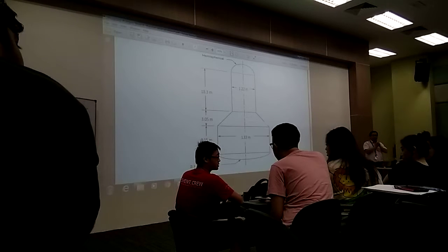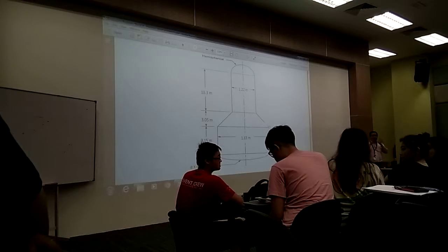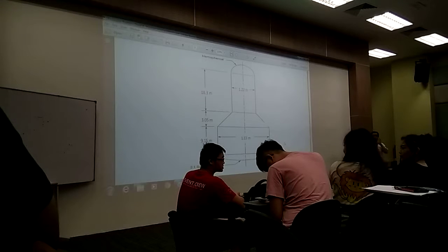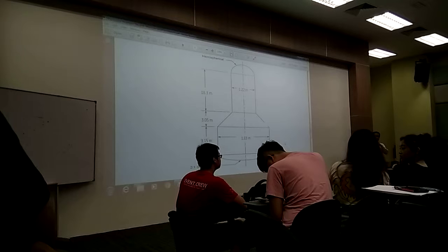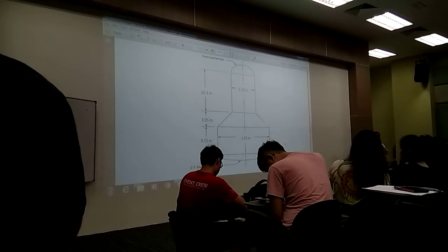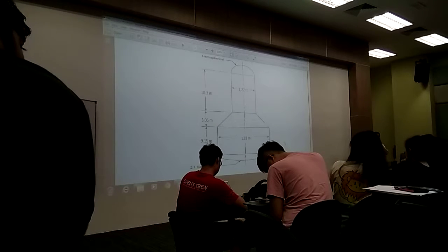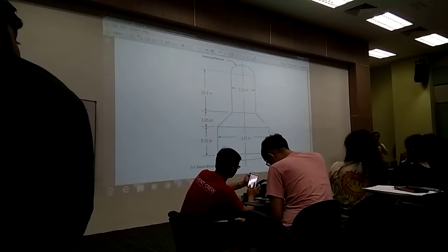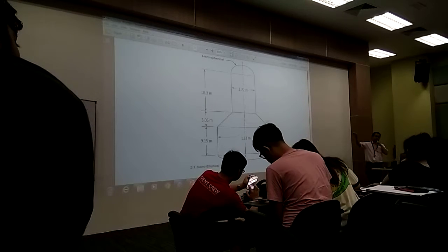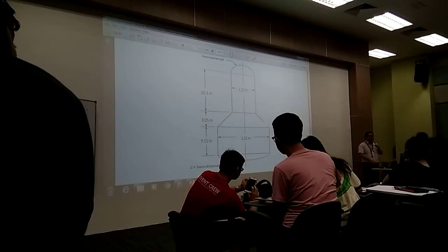And then, after that, the 7 things that you need to have before you start the calculation: design temperature, design pressure, what else? Design stress, joint efficiency factor, manufacturer, what else? I don't remember the rest.